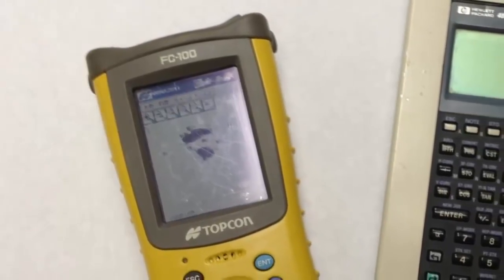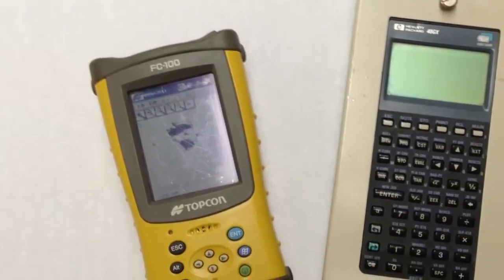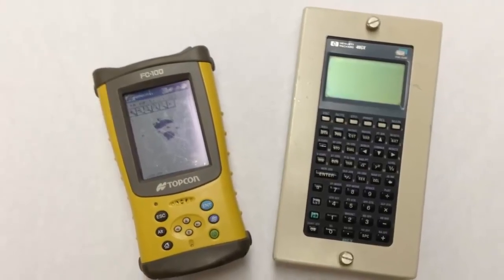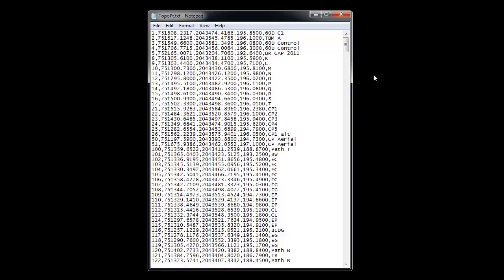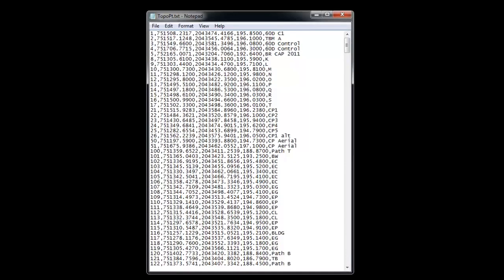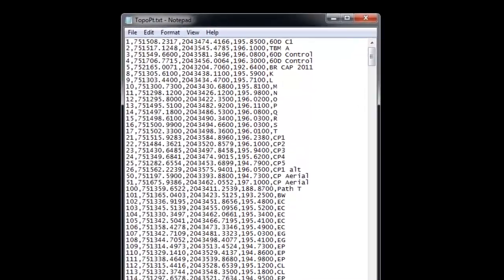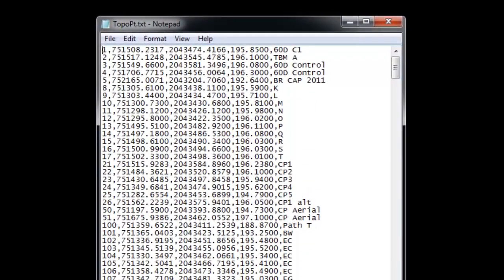Topographic surveying is a common method for creating terrain models. Data collectors, such as these, facilitate getting survey data from the field to a computer for use in software programs like Civil 3D. No matter what equipment you use, the data may be exported as an ASCII file having a .txt file extension. Data is sorted to fit one of the preferred importing methods found in Civil 3D.